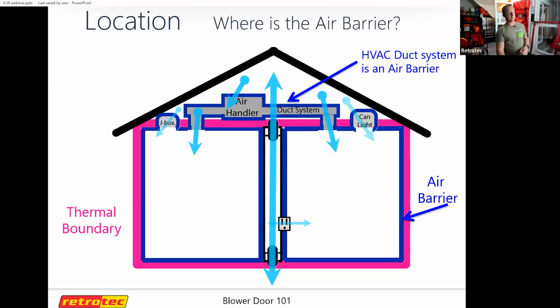And then we have lots of other penetrations that go on too. So junction boxes, electrical boxes, ceiling fans, can lights are a big one. Especially in modern homes, we love putting can lights and things. It's just more holes in the ceiling, so it's important to pay attention to deliberately air seal those. But all these places where air can get in, it adds up. And the blower door test tells us how severe all of that is when it's all added together.